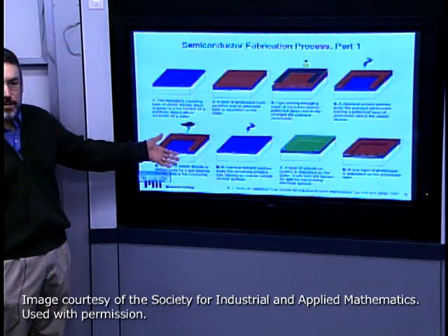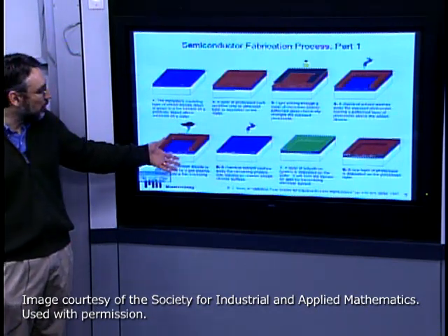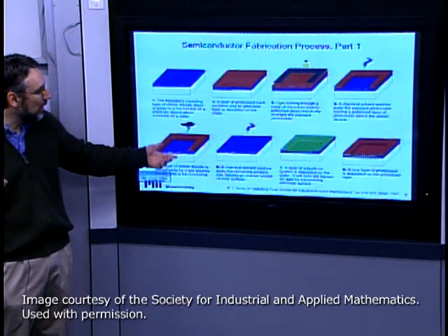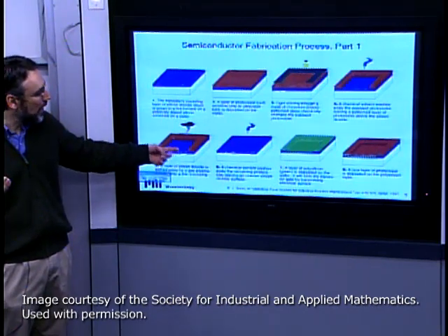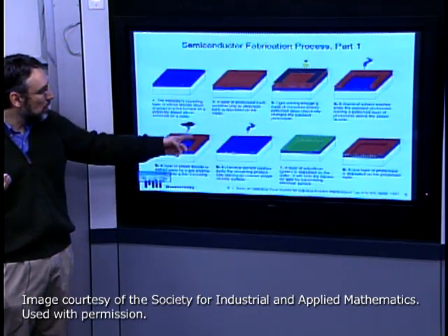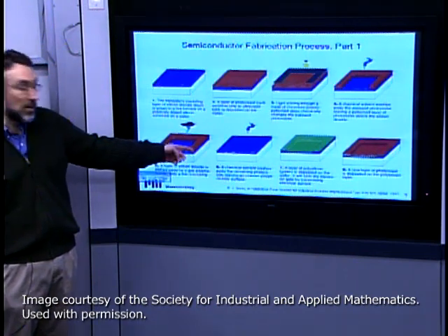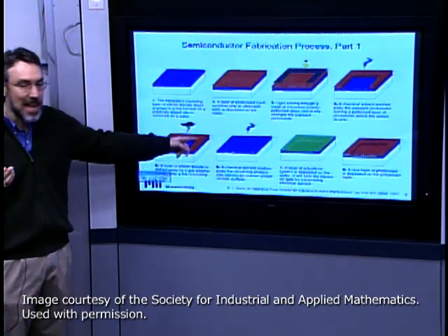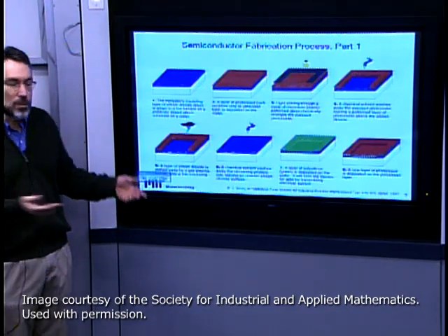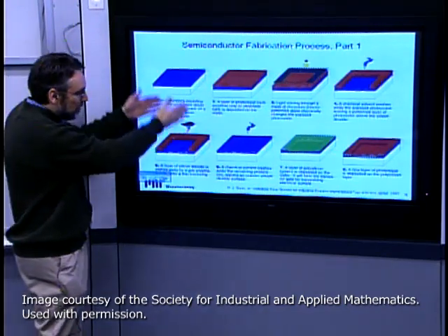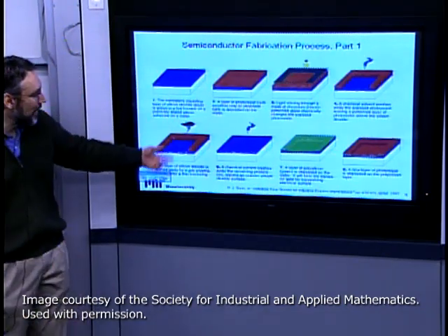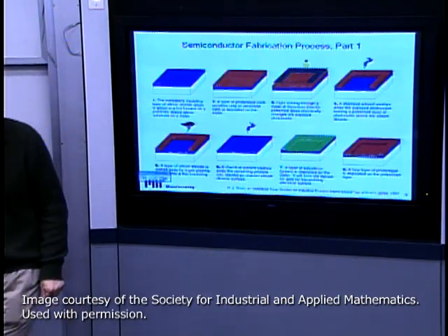So one would design the plasma process to preferentially etch away the silicon dioxide while not attacking, or only very, very slowly attacking, the protective photoresist layer. So what this is allowing us to do is essentially vertically etch down into the silicon dioxide layer.